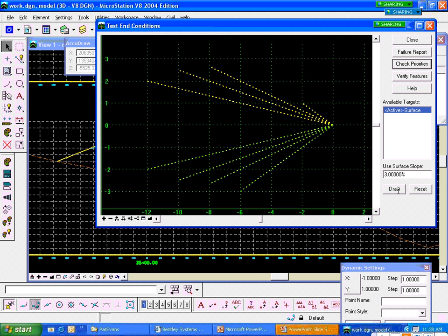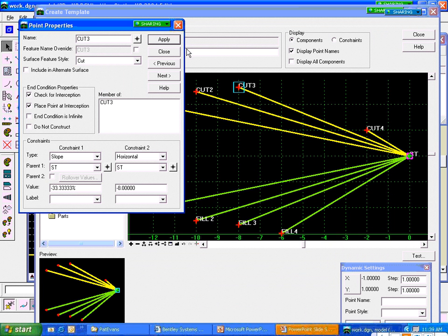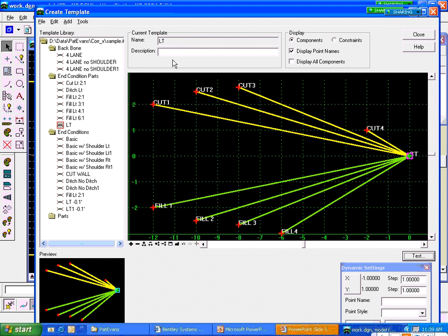Let's go ahead and we'll test this real quick. And you can see as I'm getting the 6-to-1 slope until a point. Now I'm getting the 4-to-1 slope to a point. Now I'm getting the 3-to-1 slope forever because I did not set that end condition correctly. Okay, so it's doing exactly what I told it to do. It's just I'm an idiot and should have changed that toggle right there. Easy enough to fix, okay? So that's kind of getting a little more towards what we do in the real world here.